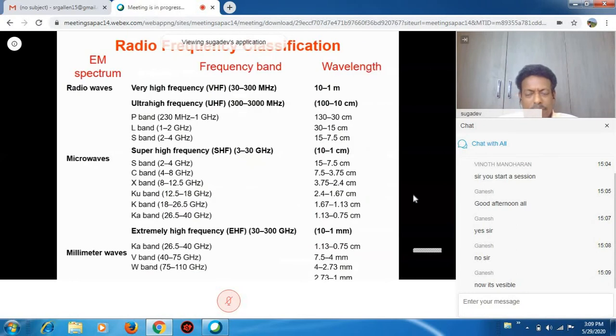So yesterday we discussed what the RF frequency range is. It is from 300 megahertz itself, and beyond 1 or 2 GHz, we name it as the microwave frequency band. And now we go up to the millimeter wave cycle. Till 100, 200 GHz, people are doing research and some commercial products are coming for defense application.